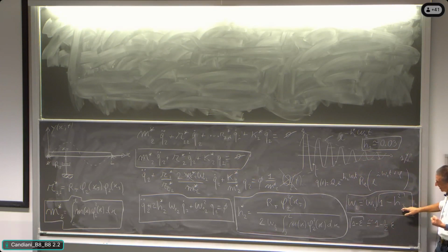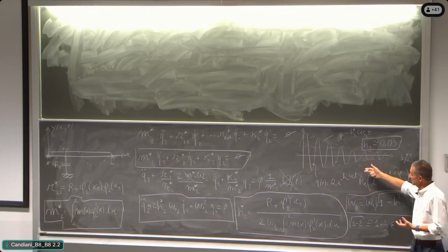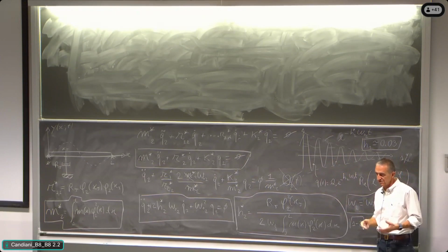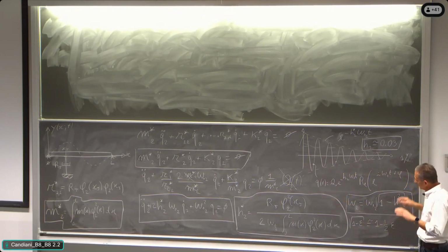And then it is necessary that we know that, all right, the theory is saying that the frequency becomes lower. All right, perfect, but how much lower? Almost not measurable, okay? It becomes much lower in case that there is a lot of damping. But in case there is a lot of damping, it is not a vibrating system. It is your car. Your car has a lot of damping, a little bit less than 1, but it is not a vibrating system. It is made on purpose in order that it doesn't vibrate on the bumps of the road, all right?